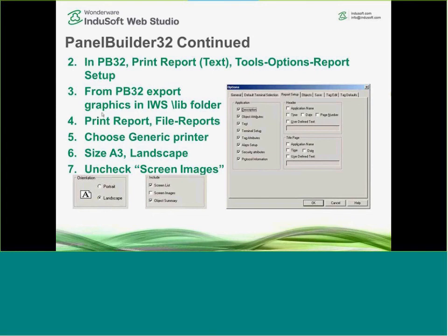The next step is to go into PanelBuilder32 and export graphics. There's an export graphics to the InduSoft Web Studio LIB folder. That's found where InduSoft is installed, not in your project folder, but under Program Files x86, InduSoft Web Studio version 8.